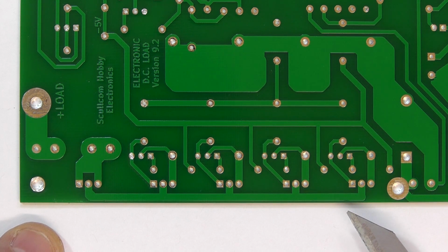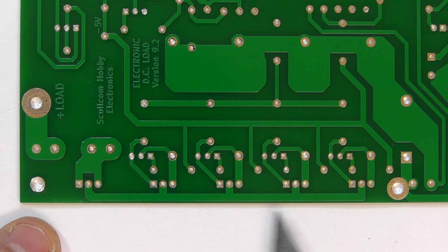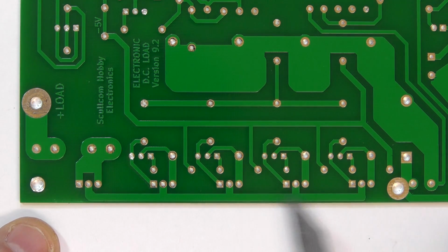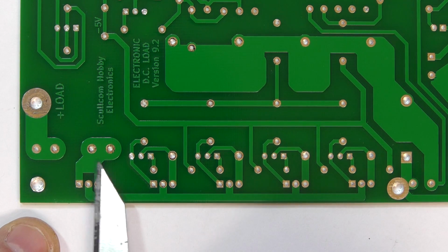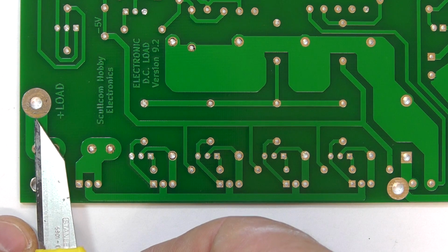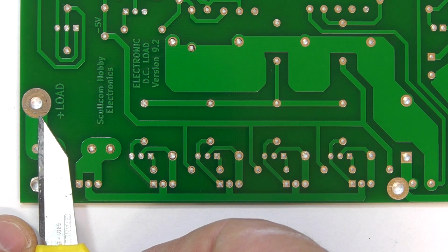It does seem to work okay up to about 2 amps with no issues, but once you get to the higher current ratings on the load, then the resistance of that track does cause a bit of an effect. So what I'm going to do is scrape the green protective coating off of that copper part of the track and expose the copper, and then I'm going to run some solder on that just to build up the current handling capability of that track. I'm also going to do the same around the fuse holder there and to the connection where you've got the positive end of the DC load.